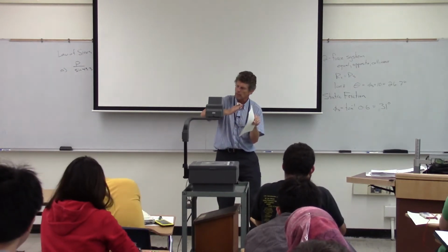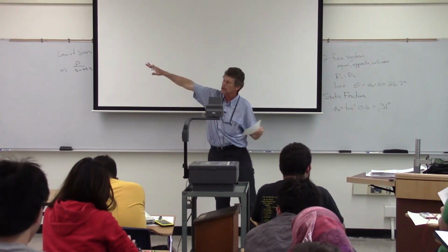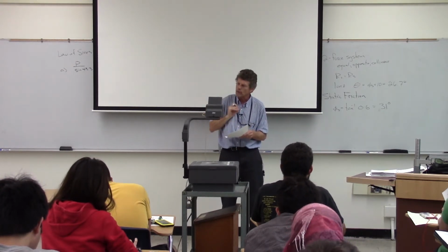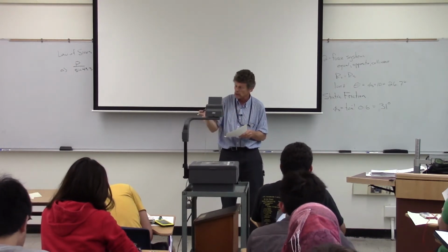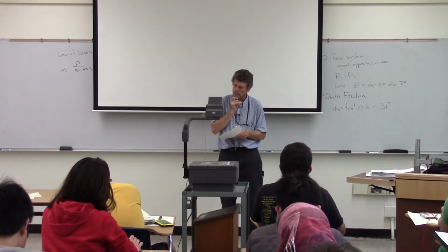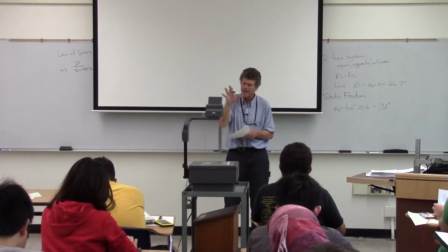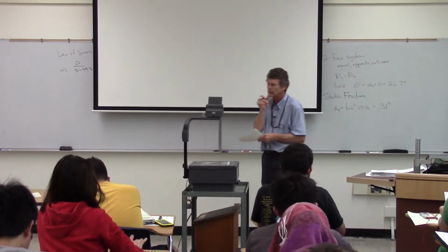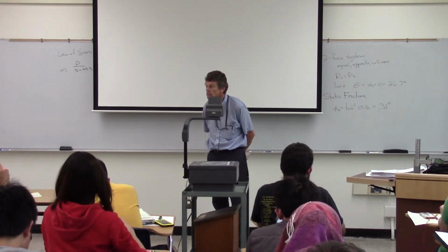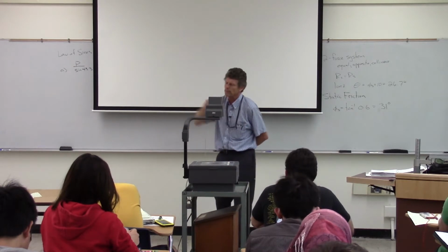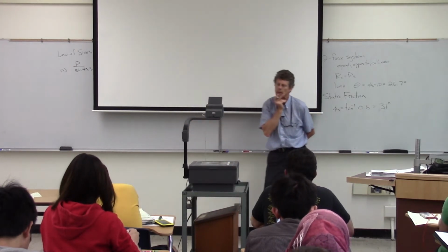So in other words, it has to pass that in order for it to go shooting out, which implies then, since my angle of the force there was less than that, it was 26 degrees, then basically it's not moving. It's in equilibrium. Are people comfortable with that? It's a little strange thinking about things in terms of angles like that. That would be phi m. Yeah, the blue would be phi m. The maximum angle we can achieve.